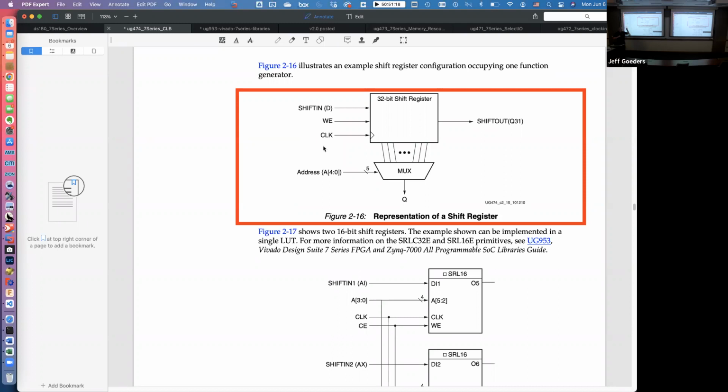Flip-flops and gates, you can build a memory, but it's very inefficient. If you know you want 32 kilobits of memory, with a custom piece of silicon they can make a much smaller memory than you could ever build out of flip-flops and gates. So they have dedicated parts of the FPGA to contain these specialized memory blocks called block RAMs.